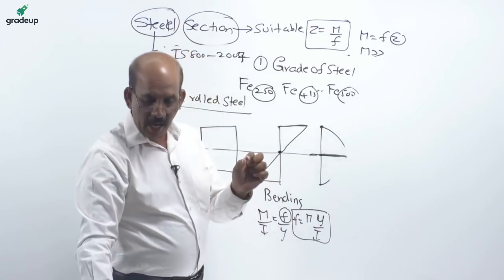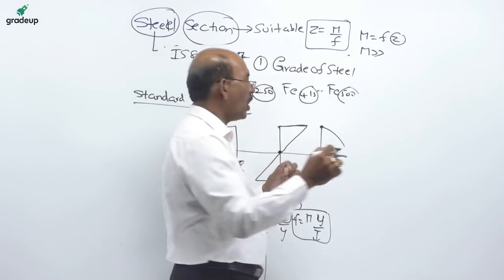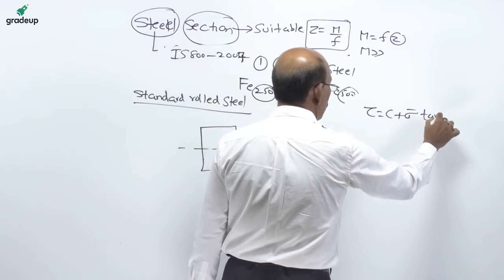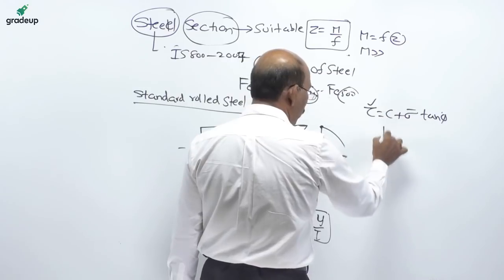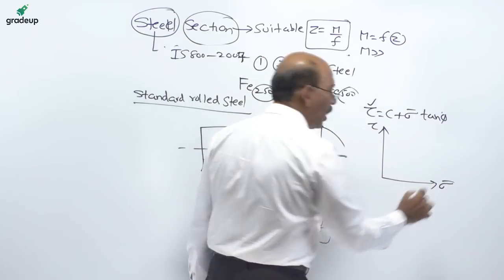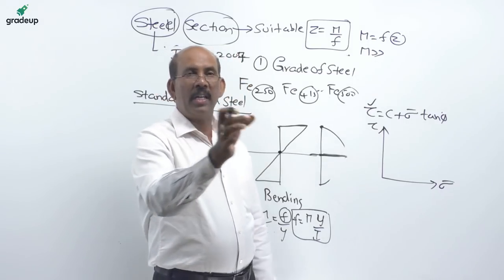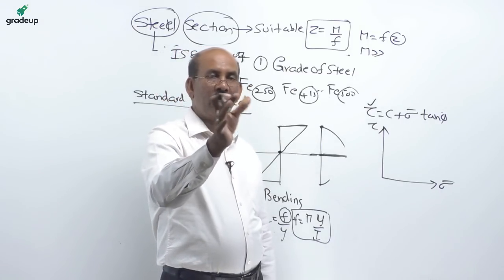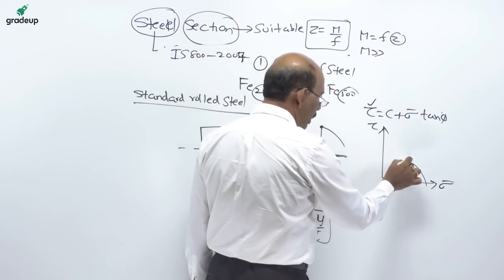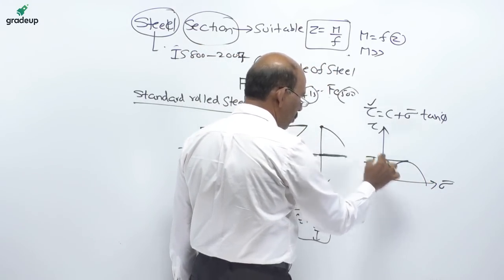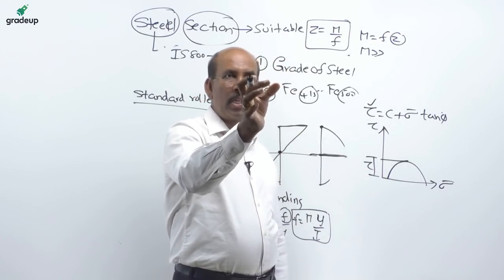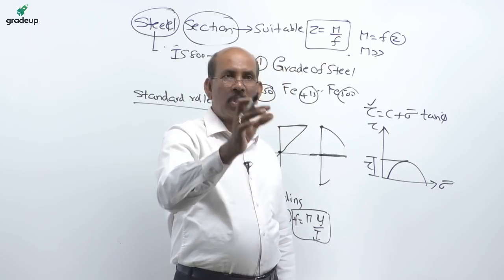This graphical representation is normally according to the shear strength of soil, tau is equal to C plus sigma bar tan phi. So tau is on the y axis, these are the normal stresses, and these are the planes on which the shear is 0. So, we are calculating this indirectly, this is the shear. This is the Mohr circle, and according to your question, draw the Mohr circle.